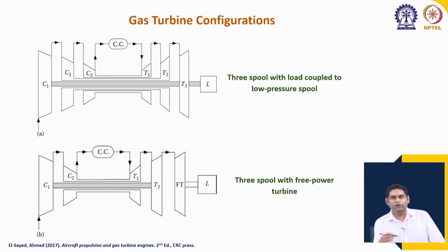For even larger turbines where we need very high efficiency and the compression ratio is very high, so that the number of stages required is very high, there can also be 3 spool designs, like 3 concentric shafts, where there can again be 2 types of cases.